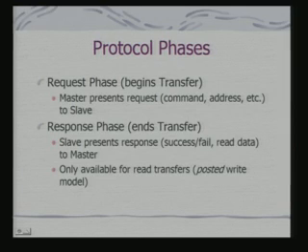Response phase ends transfer, slave presents a response, success or fail or read data. If it is a read operation, it has to be data to be presented to the master, and this response phase is typically available for read transfers. In fact, similar things were also there in the ARM, but here we are trying to evolve into generic protocol phases and protocol definitions.